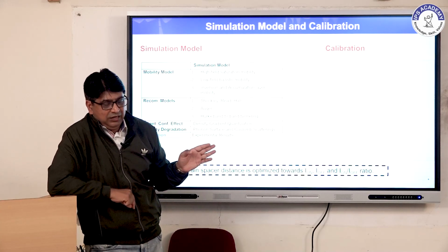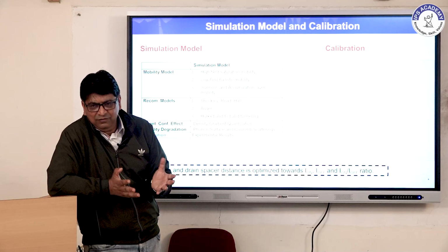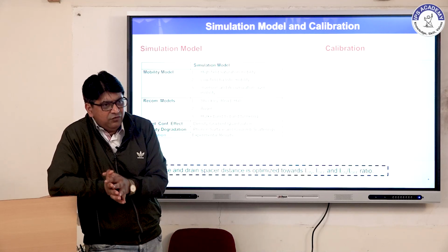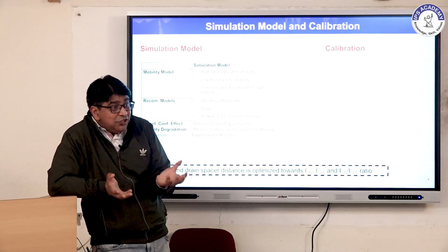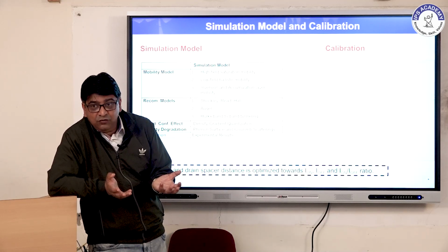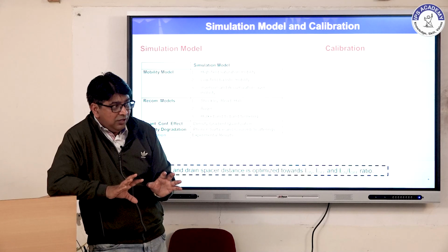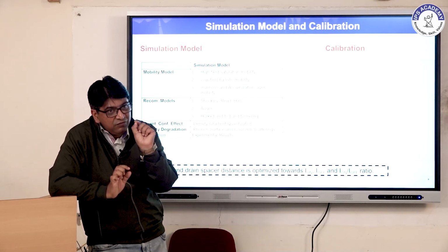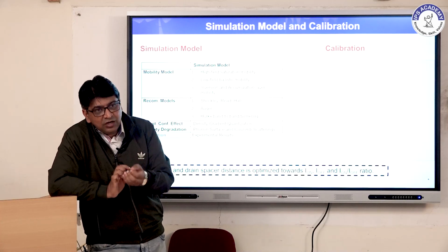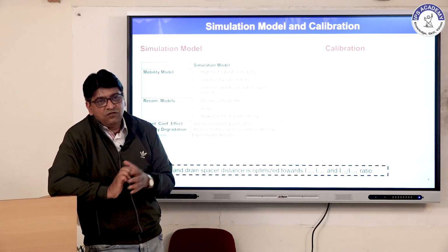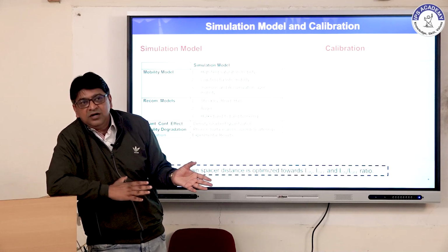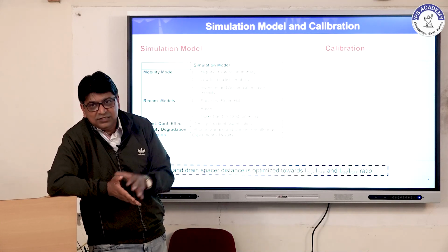In the coming slide, I will discuss some MOSFET comparison with the tunnel FET. That is a different device. So how can we compare these two devices? It is not correct to just apply the same model. At that time we have to maintain their off current on both sides, one parameter we can fix, because tunnel FET will give less off current, MOSFET will give more off current. So we cannot compare directly, because this is a different conduction concept. Tunnel FET has a different conduction. I will discuss this one.